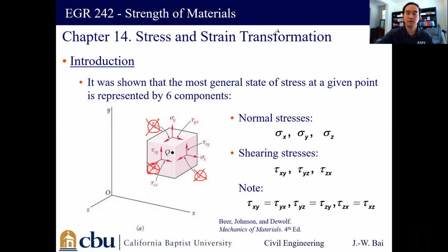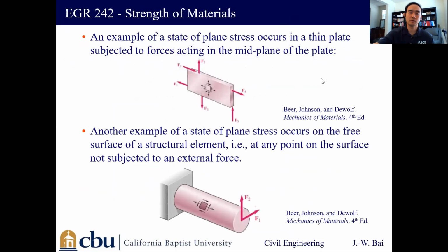And let's think about which kind of case can be classified as a plane stress situation. So here we have two examples. One example of a state of plane stress occurs in a thin plate subjected to forces acting in the mid-plane of the plate.